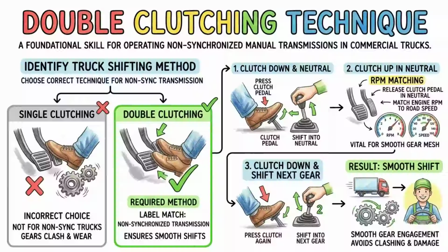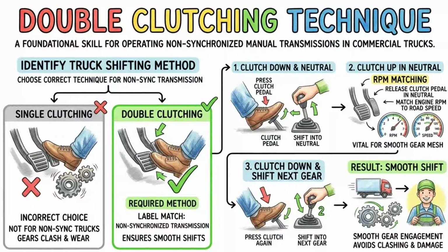When inspecting the engine compartment, you must check all your critical fluid levels. This includes your engine oil, coolant, power steering fluid, and windshield washer fluid. For the exam, you need to know that these fluids should be above the refill mark and securely capped. You will also need to inspect all the belts in the engine area, such as the alternator belt, water pump belt, and air compressor belt. The rule of thumb for the test is that belts should not have more than up to 3/4 of an inch of play when you press on them, and they should not be frayed or cracked.